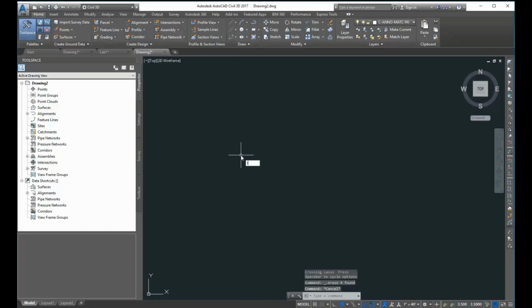So if I have a line, a couple things will show up when I start. It says specify the first point. It could be asking for coordinates, and as you see as I'm moving around, it's giving me different coordinates. Or I can just select a random point, or if I had another object in there, I could select and use those OSNAPs.